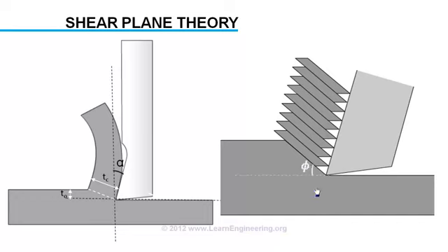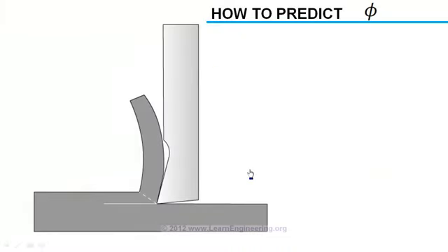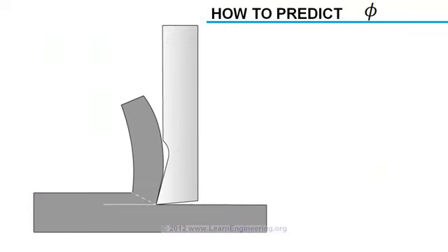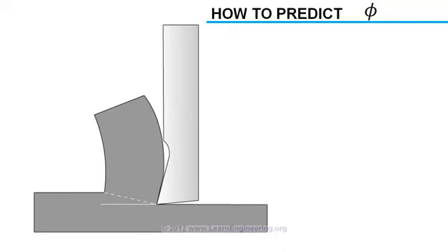If you know the orientation of this plane, or shear angle, you can easily predict chip thickness using some trigonometric analyses. But what is the orientation of this plane? That is the big question in machining and analyses. It could be at any angle during a particular machining operation, as explained in these figures. As shear angle decreases, the thickness of the chip increases.